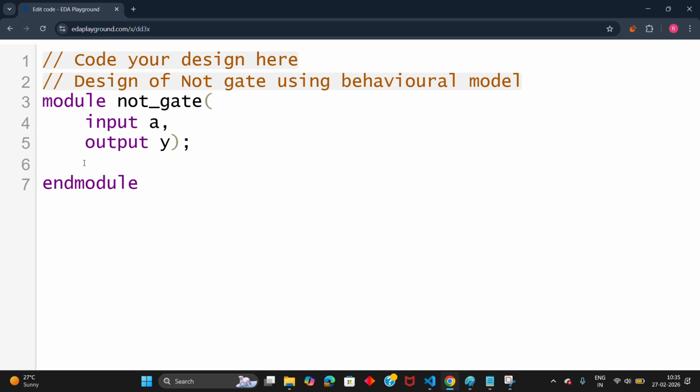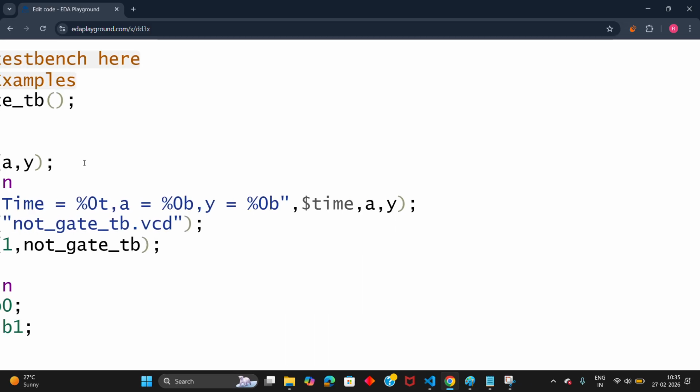The always block will be used when you need the block to be executed forever. If you need a block that needs to be executed only one time, then you use the initial block. In the Testbench we use the initial block. Why?